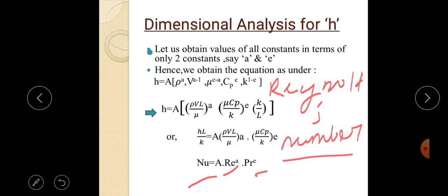At low Reynolds number, flow tends to be dominated by laminar flow, which means parallel sheet-like flow, and at high Reynolds number, flow tends to be turbulent. So the Reynolds number is the ratio of inertial forces to viscous forces.